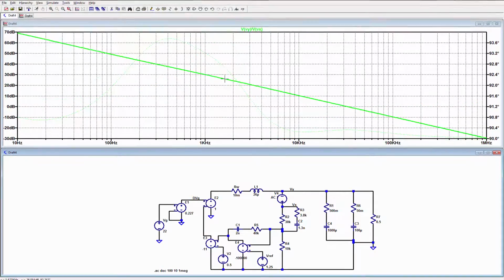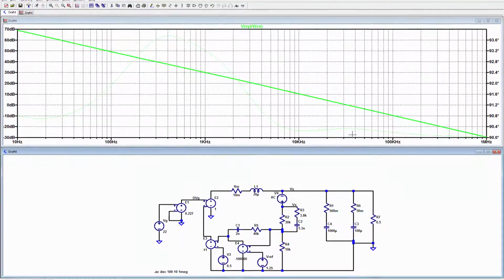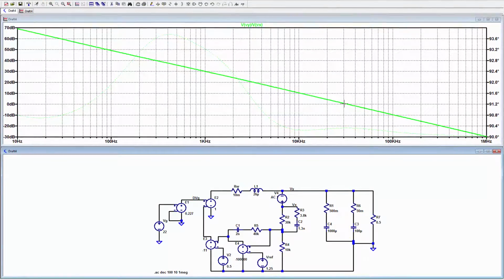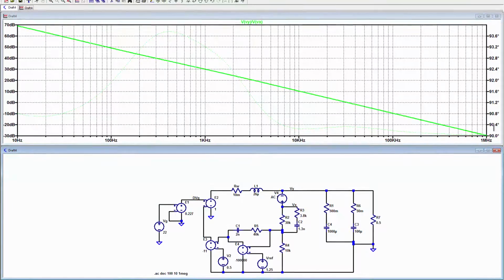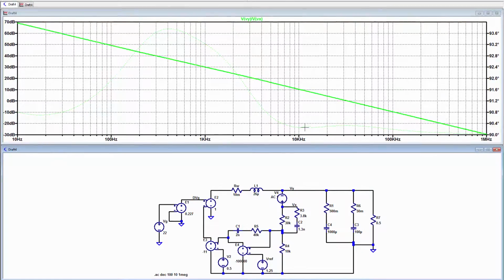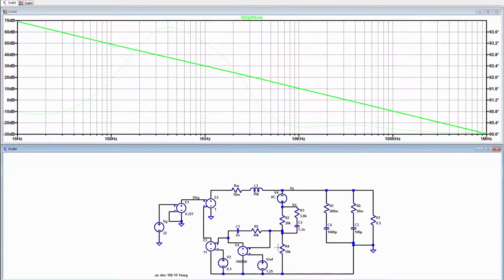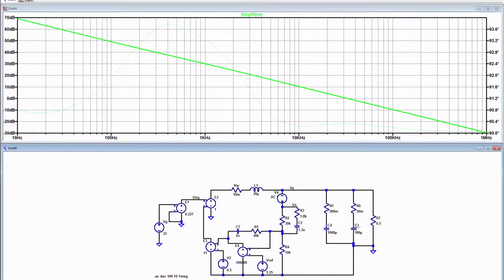And there we go. Bingo. Wow, look at that. What do we predict? 30 kilohertz. What are we getting? 30 kilohertz. Look at our phase margin. Pretty high. 90 degrees phase margin. Pretty impressive. See? So this shows that we're getting our loop gain transfer function with this circuit.